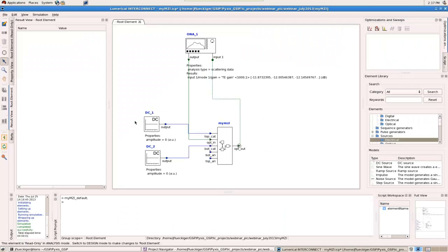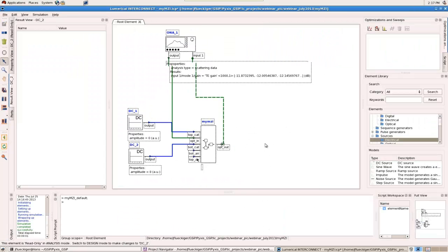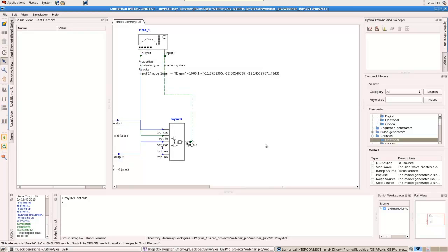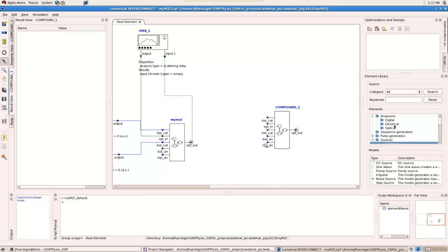So let's then do a time domain analysis. So two ways to do that. Usually I save this as a separate file, and then I just set the drivers and the sources in my eye diagram analyzer. For example, here what we did, we just used the same file. It's just easier, and it's easier to demonstrate. So I can use the same project. Obviously, when you run the project, you have more elements. It takes a little bit more time to run. But in this case, this is all real time, so it's going to be pretty much instantaneous.